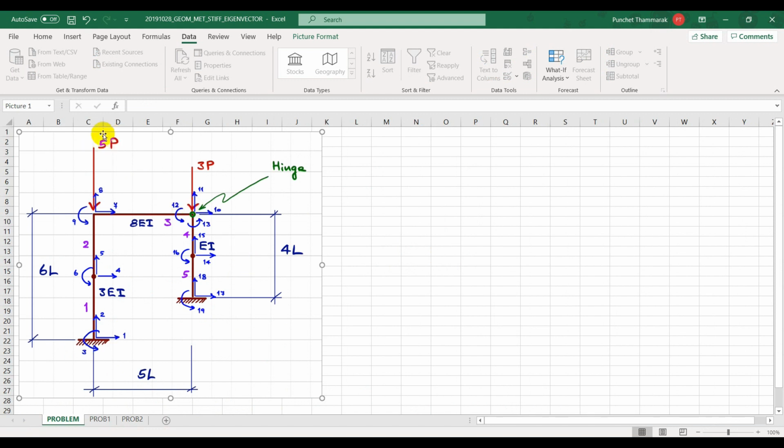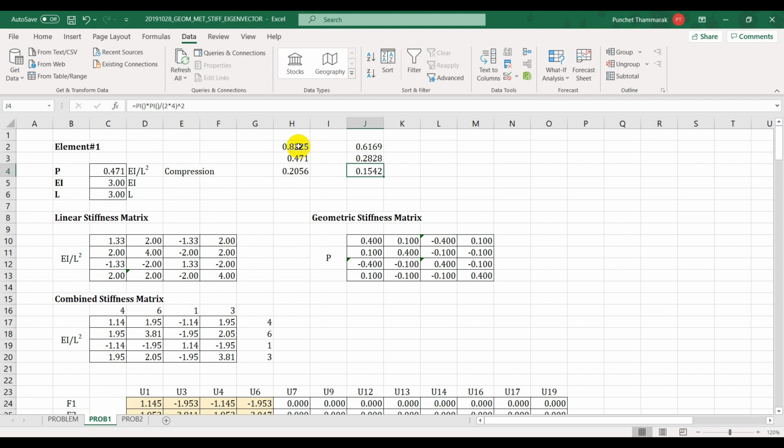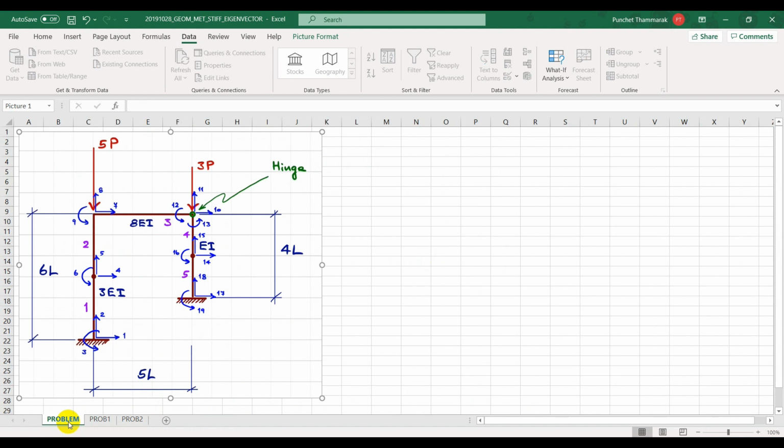Initially, in the first case, we distribute the load on the column where the column is stronger, right? If you see the buckling load of the column, you can see that the left column is actually stronger. Left and right columns are tied up with the same beam, so that means the head displacement is controlled together.